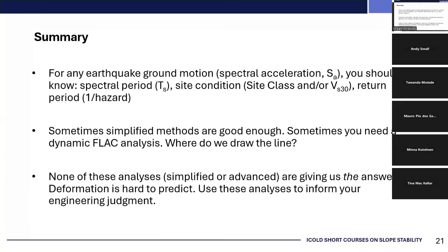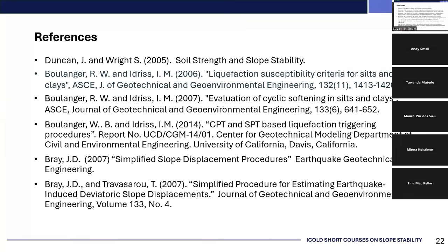During the flood, though, I may have 40 centimeters. Do I have enough freeboard? I'm saying maybe not. Just because the math is telling me I'm okay, I still need to use judgment to say, look, that's getting close to some thresholds. I need to be careful. And so therefore I'm treating that as a credible failure mode, even though the math is telling me it may not happen. So as we say here, use your judgment.